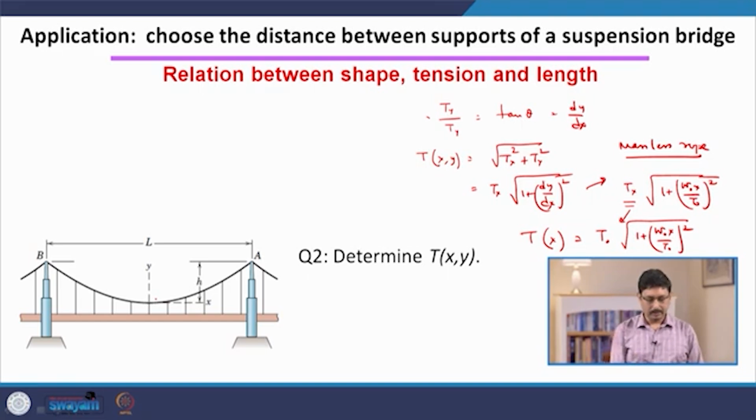So, just from physical intuition, if you look at this picture, you see that if you start from the origin and go towards the right-hand side, the tension at this point, for example, has to support the weight of the total length of this rope. As you go to this point, it has to support the weight of the total length from the origin up to this part of the rope. So, you can expect that the tension must be highest at the end point. You can plot this and verify whether this expectation matches with your plot.